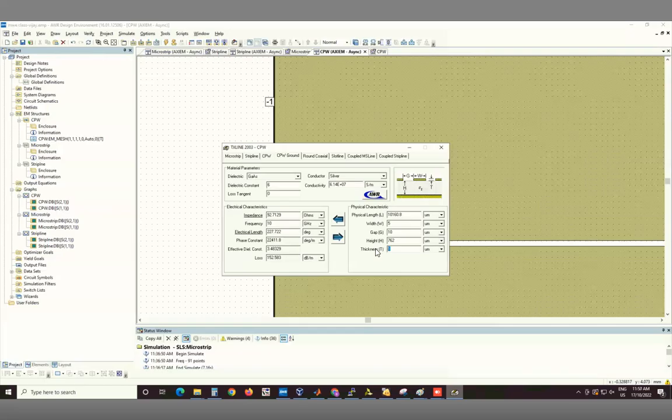So then you are much better. It's again a plane, 10 micron gap, 100 nanometers or 0.1 micron thickness. So here the impedance was so low because your two lines are now looking like big sort of 3D plates which are next to each other, right? Because this is only a 10 micron gap, but your thickness is about 35 microns. So that forms a very nice parallel plate capacitor going across your length. So that's why it was not going to very low numbers.